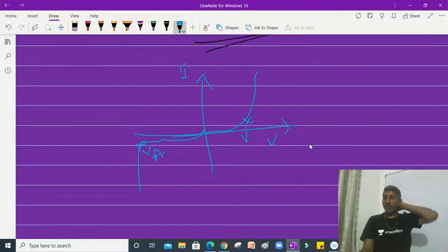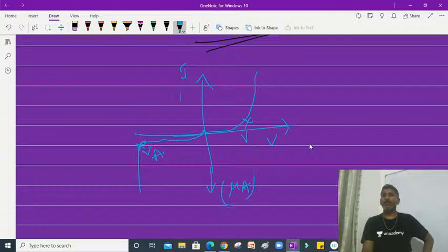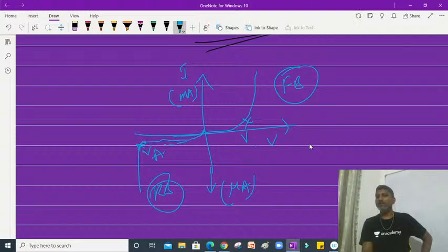Whenever electrons collide with the atoms, covalent bonds break off. Like a flood, current will increase, and it is in the order of microamperes, whereas in forward bias it is in the milliampere range. This is the forward bias case and this is the reverse bias case. In reverse bias condition, even though we increase the potential, the current does not change appreciably. At one particular potential, called the avalanche potential or breakdown voltage, the current saturates in the microampere range. In forward bias, the current saturates at the knee voltage.